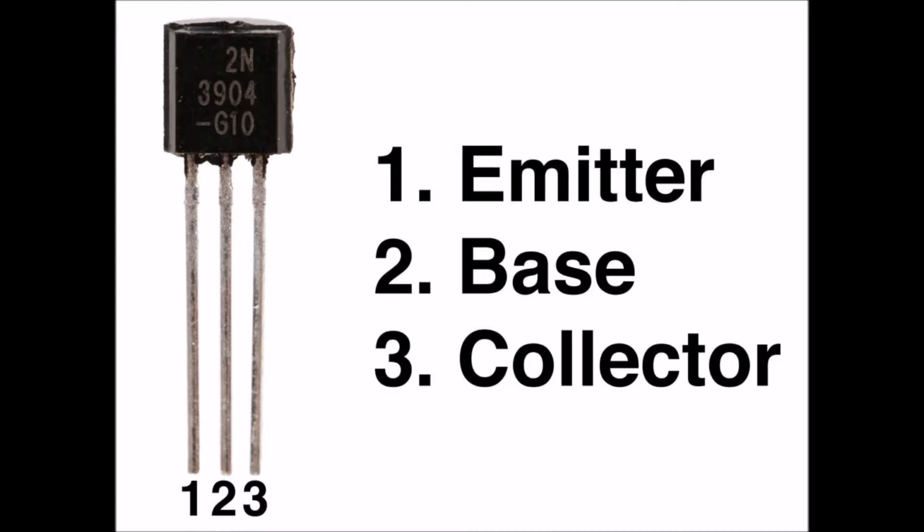Biasing. For a while, let's imagine a bipolar transistor as two diodes connected in reverse series. That is, in series, but in opposite directions. We can't normally connect two diodes together this way and get a working transistor, but the analogy works for modeling, technically describing the behavior of bipolar transistors.